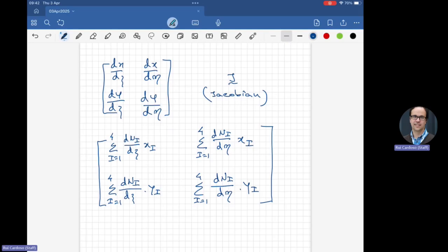You will have a stiffness that is given, and you have a fixed mass. So what we are doing here is basically the same thing, a stiffness and a mass, but in the context of finite element analysis. Then we go to the central difference method and do the time integration. In your coursework, you will also have a stiffness and a mass, and you need to use the central difference method as well.